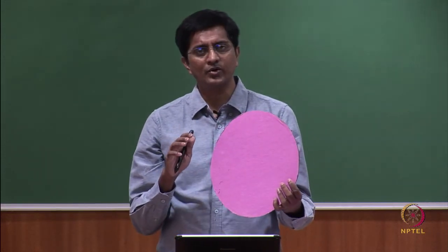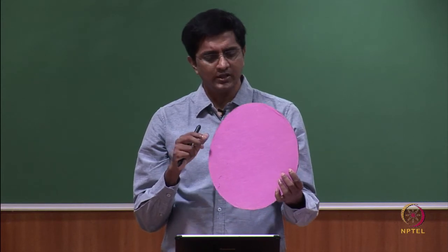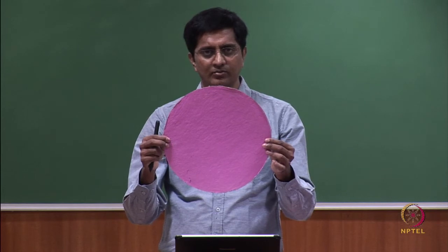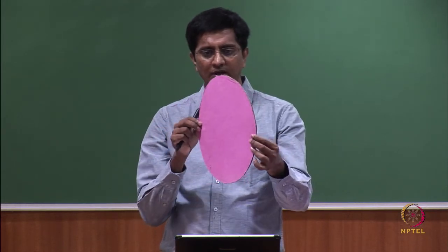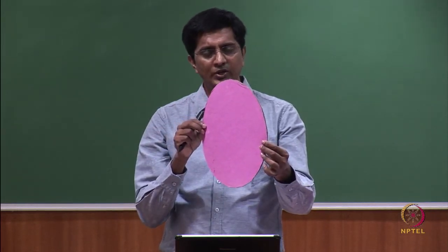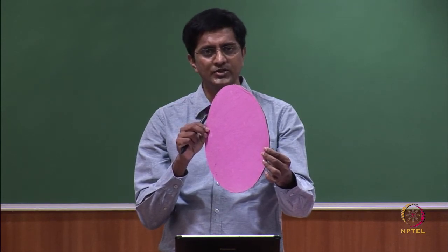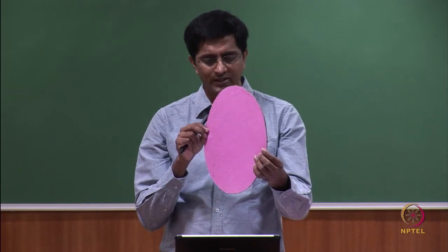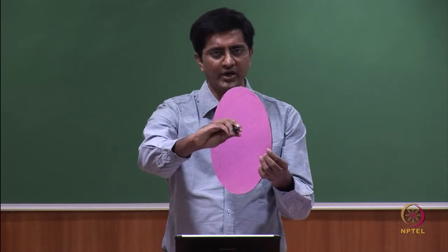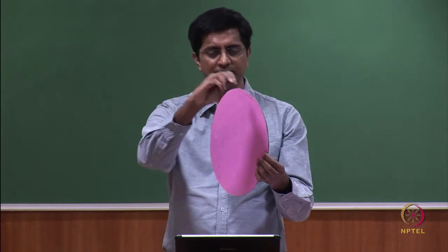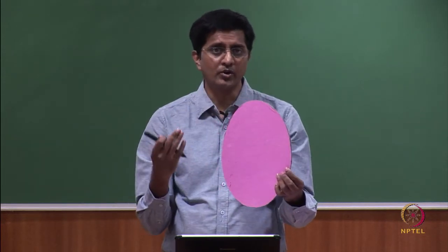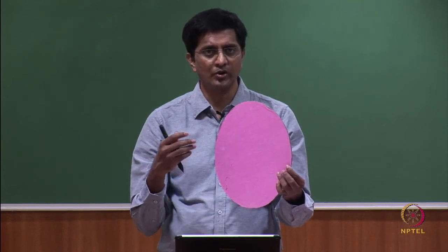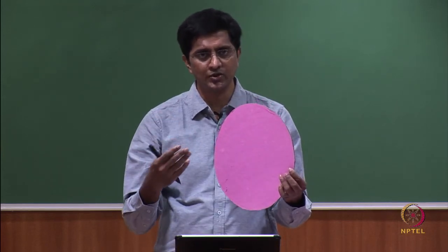Again, what I want to demonstrate here is, if you look at the front view, it is a circle, but the moment I change the orientation, will you still see it as a circle? Will you see the true shape of this circle? No. The answer is, at this angle, if you are looking from the front, what you notice is an ellipse. So, now you need to know how to draw an ellipse on an engineering drawing sheet, because you want to make sure that the ellipse looks very smooth.